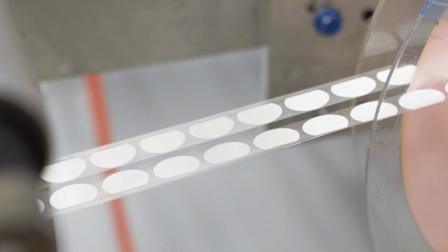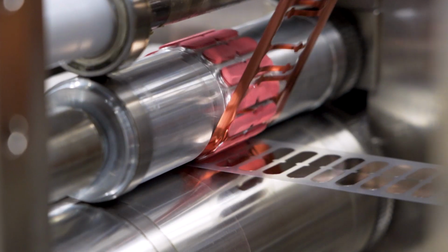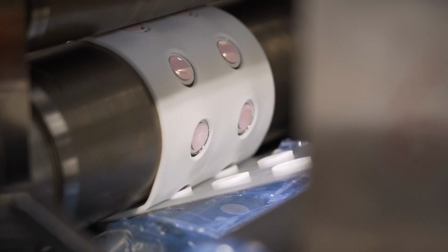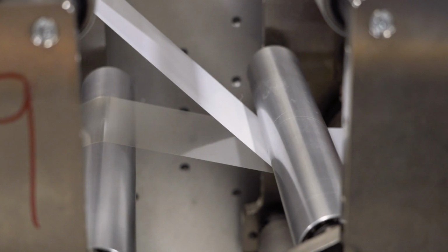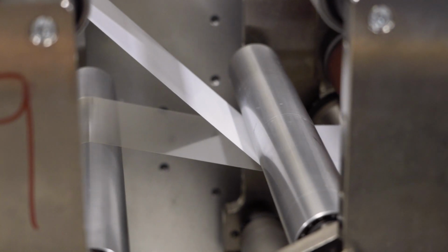On the other hand, film liners offer higher durability and cleaner die cuts, which makes them a better fit for demanding environments. They are also more resistant to tearing and offer more flexibility in terms of coatings and thickness options. However, film liners are less compatible with standard printing methods, making it difficult to add registration marks or sensor indicators, which can be crucial to automated production lines.